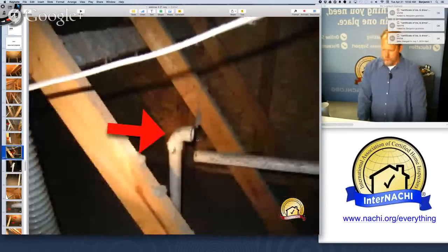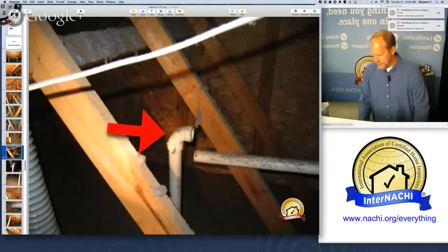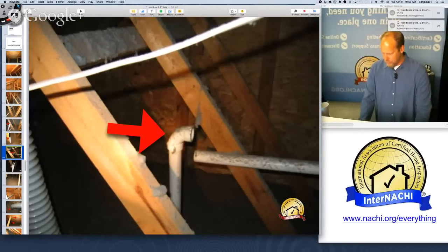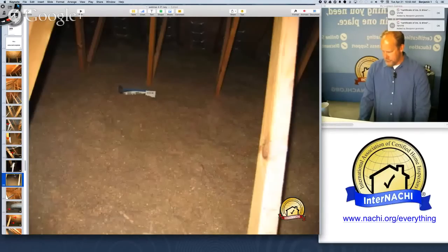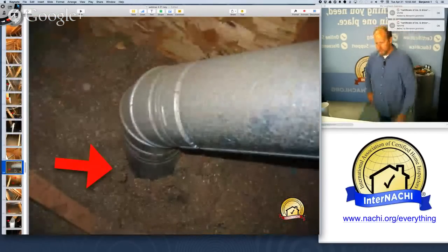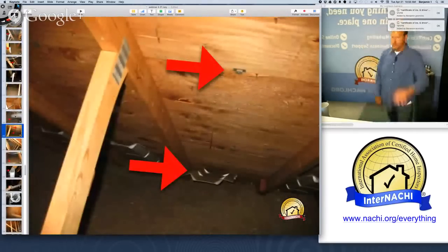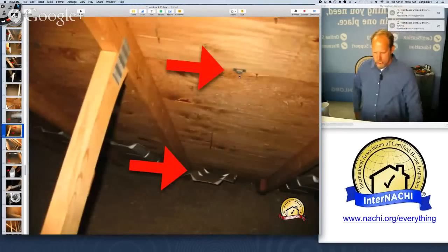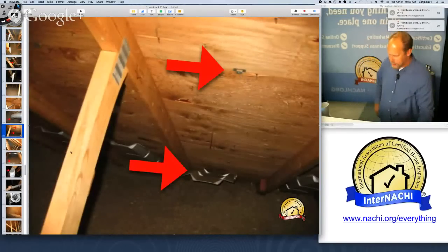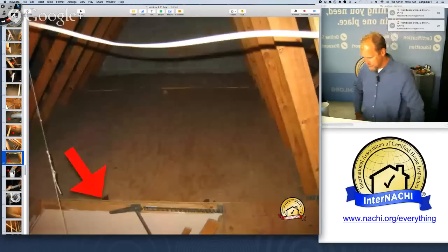And also have disconnect of the vent pipe from the drain waste vent pipe system. That's disconnected in the attic. Just found there. I didn't pull it apart. It was just found like that. And the insulation looks okay. I don't see any roof leaks. I like to see if there's a fire break, a wall there, a collar, where the stack goes through into the attic space. I'm looking at clips, plywood clips. I'm looking at the ventilation trays. I'm looking at patterns, so I can easily see everything is in alignment and balanced, nothing out of place